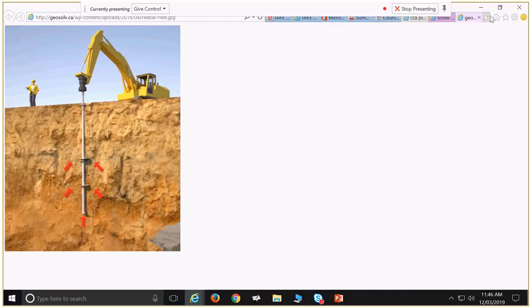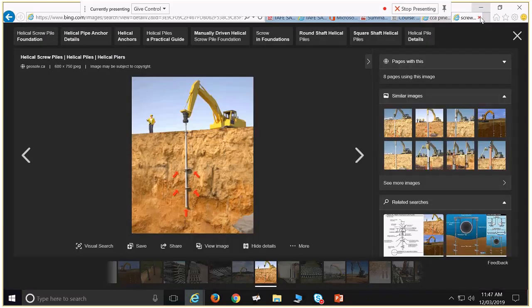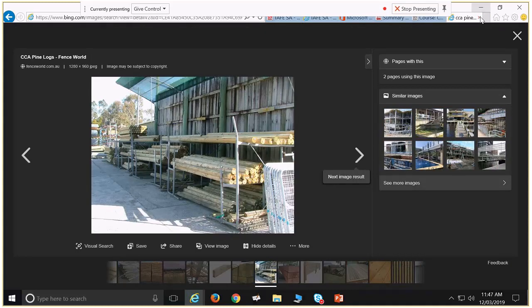Oh yeah, one thing I was going to say though, with the installation of your screw piles, it can go fairly quick and easy as well. Because your auger just drives them down there, and it typically takes two people. You've got somebody in the excavator, and then somebody standing there with the screw pile and their spirit level, and they say okay, it's right, and they tell the excavator driver to move forward and backwards, whatever, to get that screw pile directly straight, start driving it, keep checking it, and then drive it in. So that's the process in which it happens.